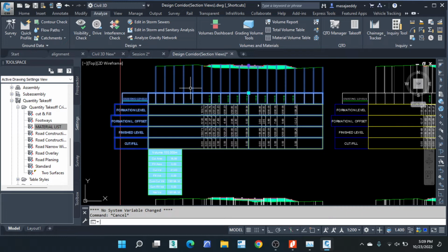Instead, they are going to use something that is higher, so that when they compact, it becomes the actual value. So there is always a compaction factor in this case. So you get this value times the compaction factor, then you get the actual value that's supposed to be quantified. For example, you have 193 cubic meters times, if the compaction factor is 1.5, then you get that value.